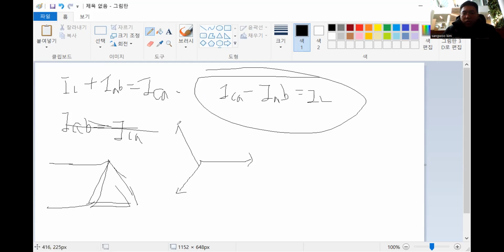That's why we also need to learn Kirchhoff's laws and the phasors. It's really important to draw this. That's why we learned it. Look at that. So we have three currents, right? I_AB, I_BC, I_CA, right? I will say just 1, 2, 3, okay? But I_line is I_CA, number 3, right? From here, but minus I_AB, right?